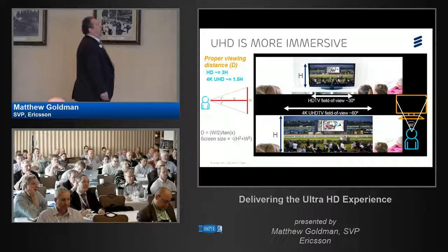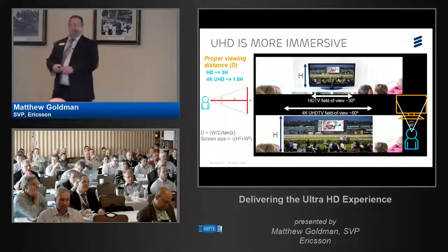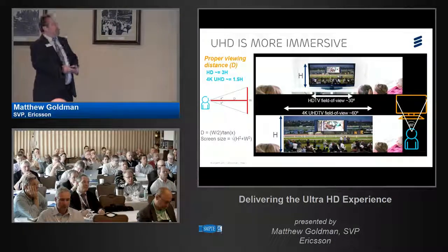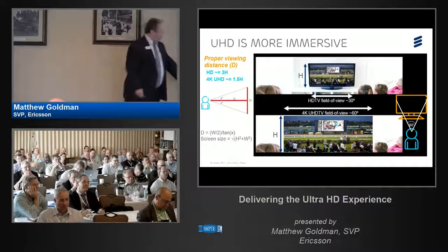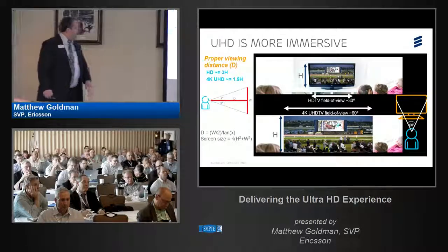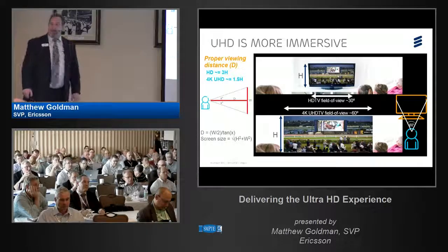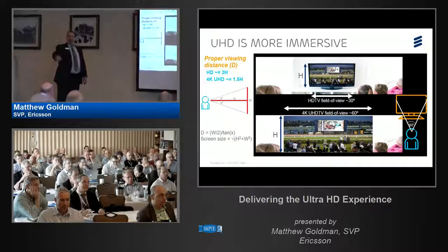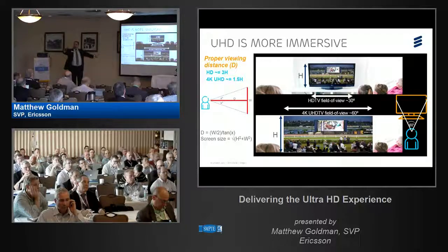But for the resolution of 1920 by 1080, which is everybody's HD in the panels today, the proper viewing distance is roughly around 3 picture heights back from the display. So if this is your display here, this white area, you measure that back. One distance for that is about right here. Then you measure out 2 more. So it basically is saying that somewhere around the 2nd or 3rd row is the last thing that you'll see if this was HD, the resolution of this. If you're further back, you can see the image, but you're not seeing all the resolution. Okay, it's very important to note that.